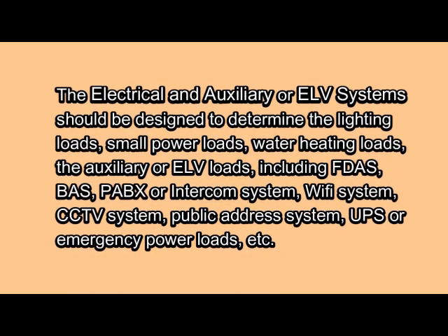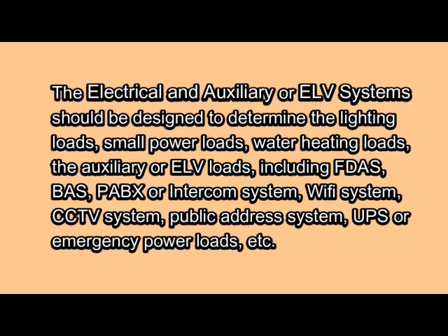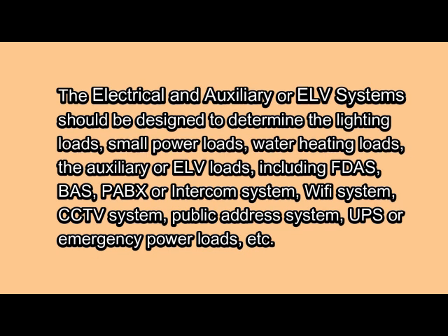Then the electrical and auxiliary, or ELV, systems should be designed to determine the lighting loads, small power loads, water heating loads, the auxiliary or ELV loads, including FDAS, BAS, PABX or intercom system, Wi-Fi system, CCTV system, public address system, UPS or emergency power loads, etc.